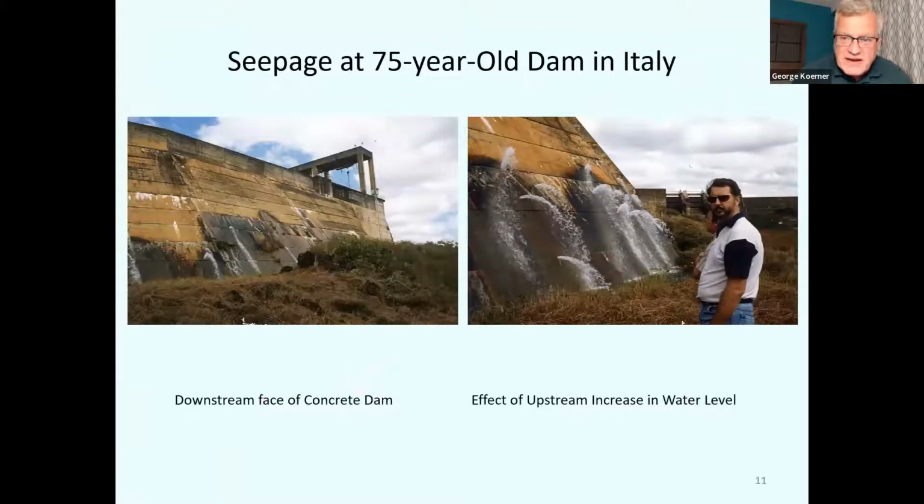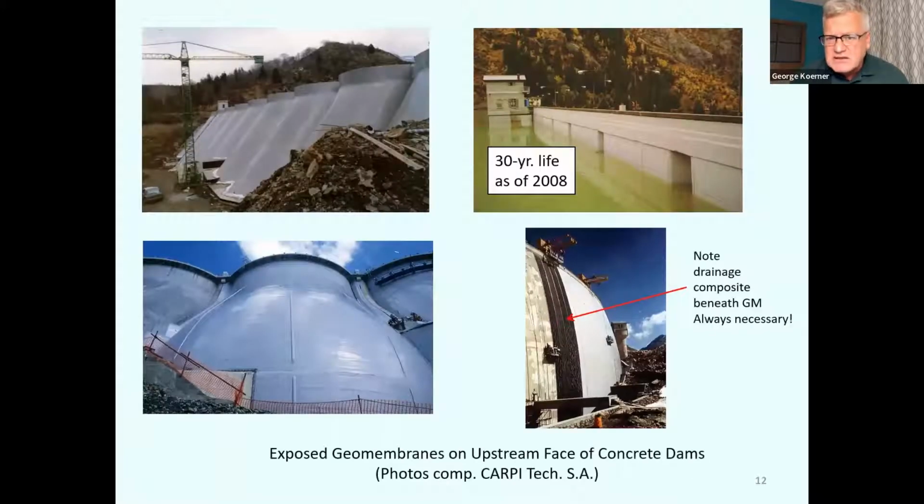So for people in the landfill business, we are talking about different hydraulic heads here. These hydraulic heads are massive, and what that does is exert tremendous pressure on the geomembrane. So the membrane has to be much stronger and much more robust than for a surface impoundment or a landfill cover system. The systems look like this. They're quite stout, with geomembranes up to 5 millimeters thick, which are placed.